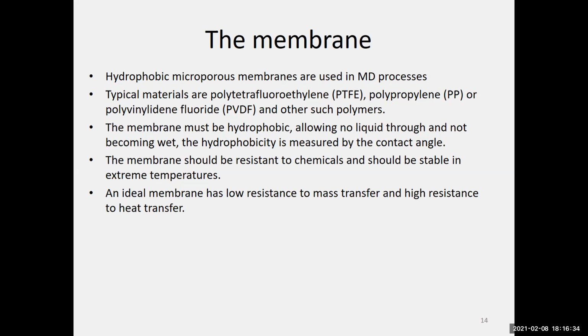However, for membrane distillation, the kind of membrane we are using here is a hydrophobic membrane that does not allow the water droplets to pass. It only allows the water vapor. Can we have a surface that does not allow the water droplets to penetrate through? Yes. All the waterproof surfaces are like that.